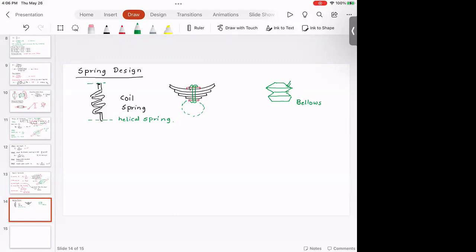So in trucks, the cheapest way to do that is using a composite spring. What do I mean by composite spring? You have this eyelet and the spring is attached over here, and the other base of the spring is attached over here. So right now the attachment points for the spring are this and this. Now, if you want to change the stiffness at runtime, how would you do it? You can do that by adding or dropping coils, or adding and dropping leaves. So please observe this: on trucks, there are additional attachment points over here.